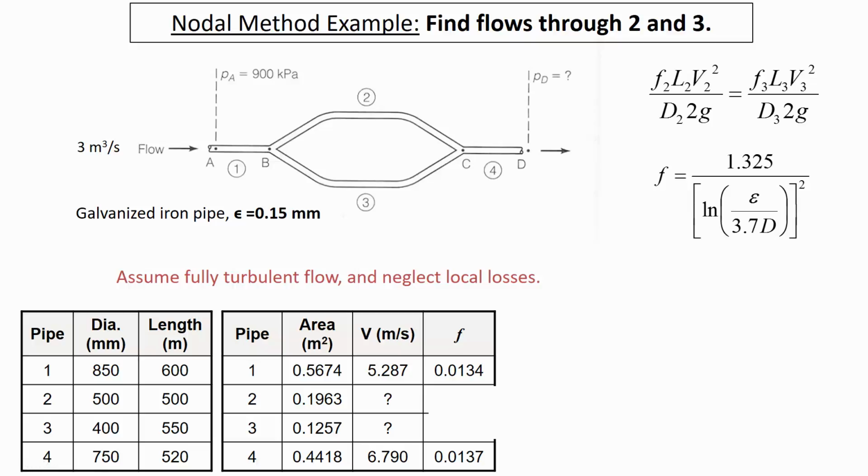Now here's a really important thing. Anytime you use that assumption, you have to check to make sure it's valid. You can't use it unless you check later on. So keep that in your mind, that after you find the flow rates, you're going to use the Reynolds number and the full version of the Jain equation just to make sure that the F value you calculated using the fully turbulent flow assumption is within 1%. We'll say that a 1% difference is our threshold for needing a whole new step of recalculating everything based on an updated F value versus just saying it's good enough.